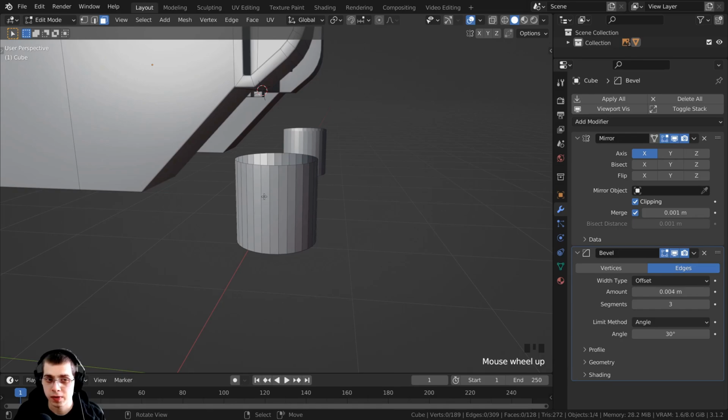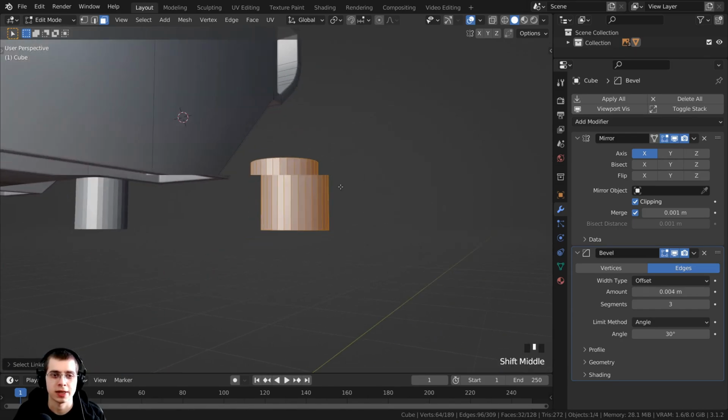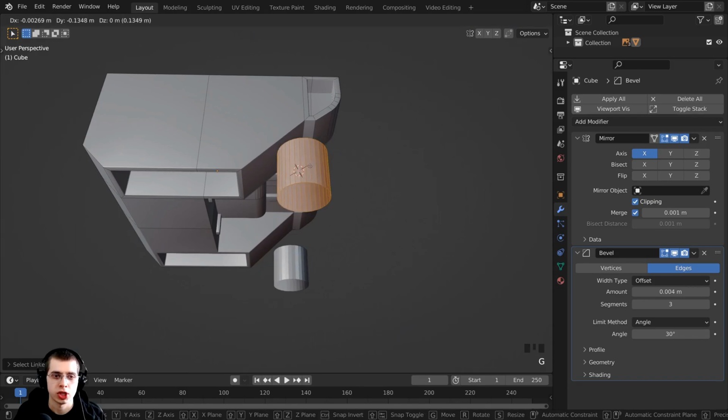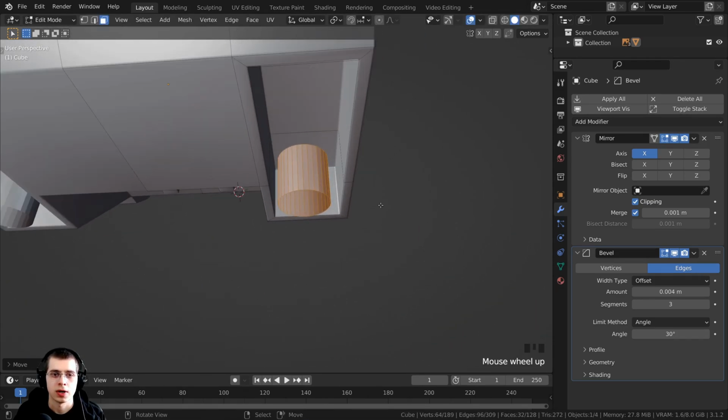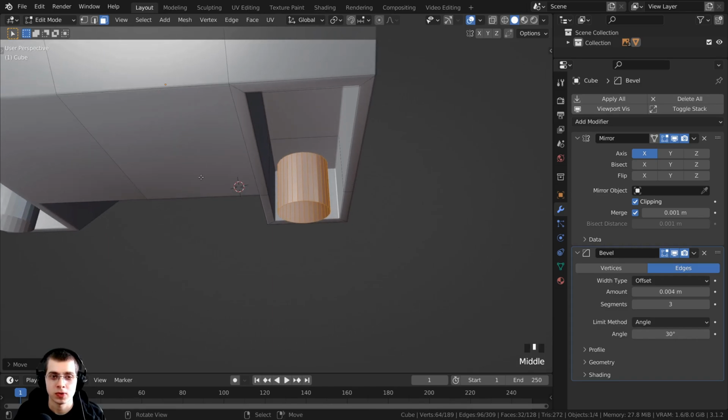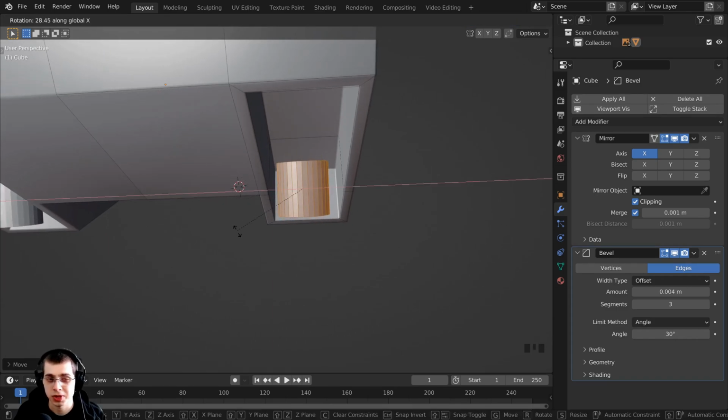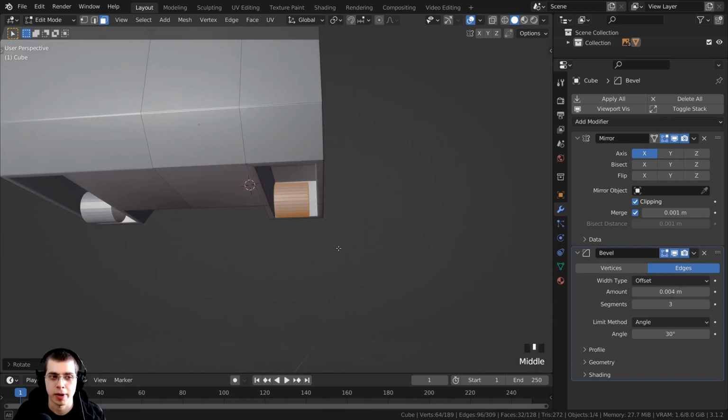And then hover your mouse over this object and press L, that will select the linked vertices. I can press G to grab, and S to scale, and we're just going to bring this in. All right, so I now want to rotate this over. So I'm going to press R to rotate. Let's rotate this on the Y axis, and then I can type in 90 and enter, and that's going to rotate it exactly over by 90 degrees.